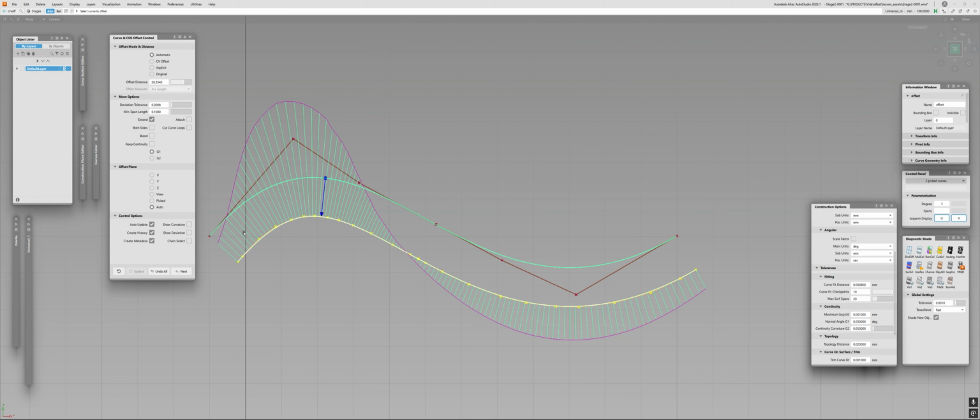If you don't want a million gazillion spans with extremely tiny lengths, which you don't want actually, then be reasonable with that. Now, my tolerances are very, very tight because I'm working with a lot of small objects and consumer electronics. But for a car, for example, these parameters make zero sense.